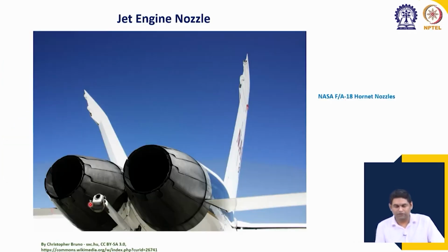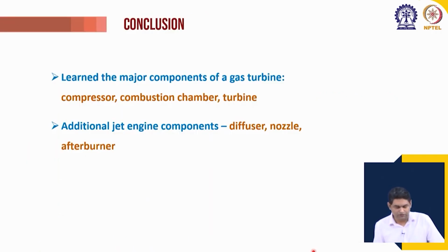Okay. This is another example of a jet engine nozzle. You can see that this is a convergent nozzle, the size is gradually decreasing, which is the typical case for most aircraft, unless it is a very high cost, high speed experimental type aircraft like scramjets. Otherwise, we can use convergent nozzles, and these have other features, like movable flaps. These flaps overlap more or less depending on how much cross sectional area is needed, which needs to change based on the volume flow rate through the nozzle. This is from a military aircraft, and you can see how the nozzle shape varies.